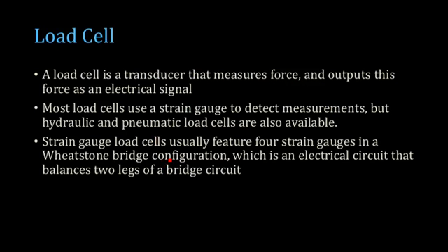Now load cell is a kind of transducer. It's a different kind which measures a force and gives an output in terms of electrical signal. And this load cell is actually an application of strain gauge that we have already seen. So load cell is an entire structure which houses the strain gauges, and it not only uses strain gauges, it can also be used along with hydraulic as well as pneumatic arrangements to measure the force.